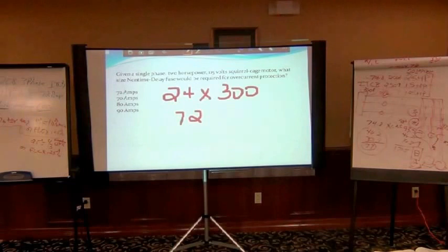Now, you can see real easy, I can get every one of those 4 answers depending on how I apply the exceptions. The calculated value is the top one. A lot of guys make the mistake of choosing 72 because that's your calculated value, and don't bother to go back and realize that we're talking about a standard fuse size, and they don't make a 72 amp breaker or fuse that I've ever seen. So get that out of your head.